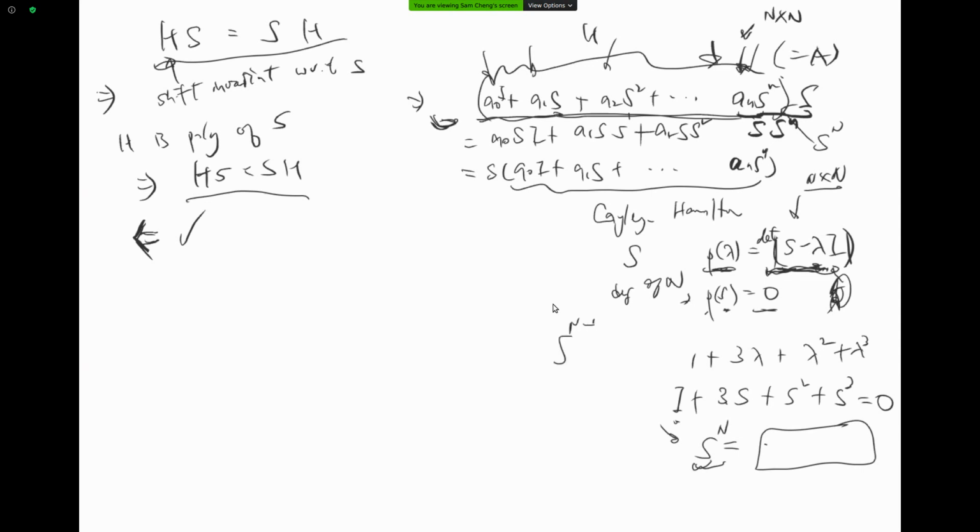Therefore the only coefficients that are meaningful, that can uniquely represent a different filter, are n coefficients, from 0 up to n minus 1. So the degree of freedom of this representation is only n.